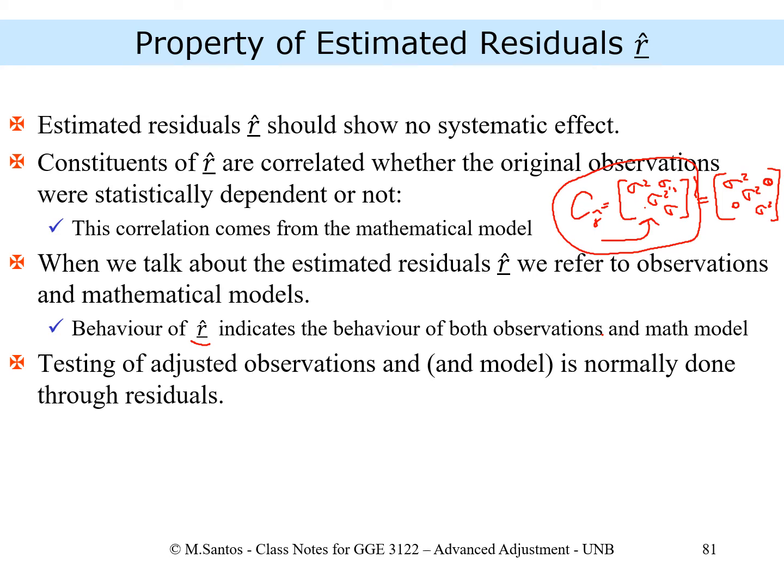If you're shopping for an estimation package, an adjustment package, and it doesn't provide residuals, get rid of it. It may be good, but it's missing one thing that is very, very important. We learn a lot from the residuals. That's why the tests on the estimated parameters after the multivariate tests use residuals quite a lot.